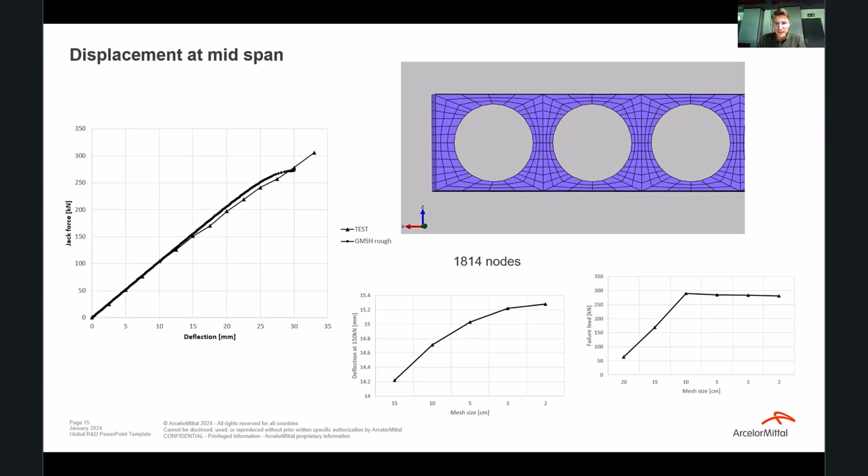150 kilonewton, and you see that for a mesh size around 3 centimeters it starts to be quite consistent, but we overestimate the stiffness for larger mesh sizes. And for your information, this picture that I put is around 5 centimeters, the size of the mesh. So we overestimate a bit, it is the triangle in the middle here.